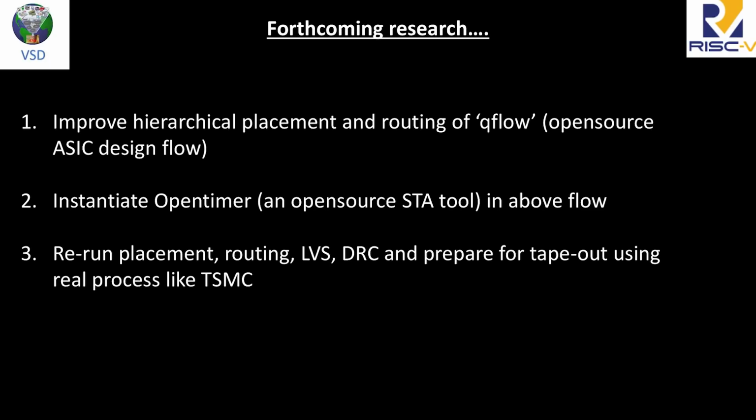The next step is that we want to improve the hierarchical placement and routing of Qflow, because right now Qflow is very good for flat implementation. There is a company called eFabless.com where we taped out a chip, a PicoSoC. We did a flat implementation using the XFAB 180 nanometer process, and we taped out using the entire open source tool chain. So we know that Qflow works very well for a flat implementation. The existing infrastructure needs to be extended to support hierarchical design. That's the next challenge we are targeting.